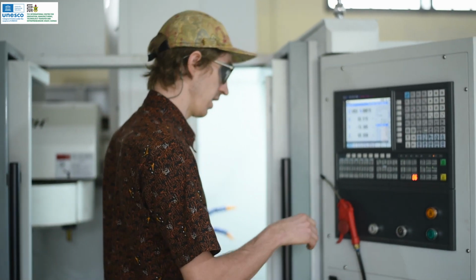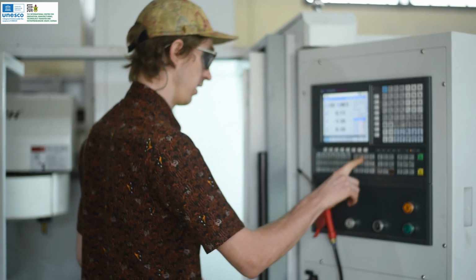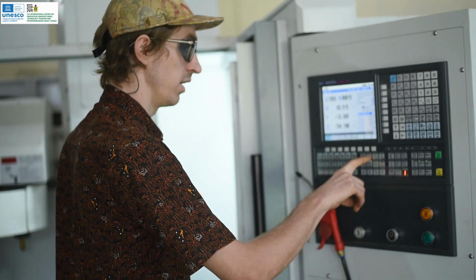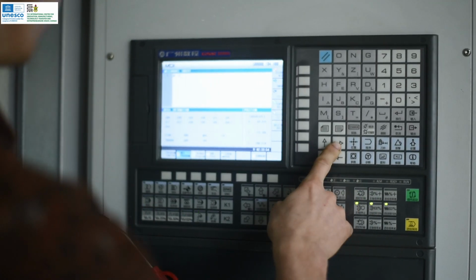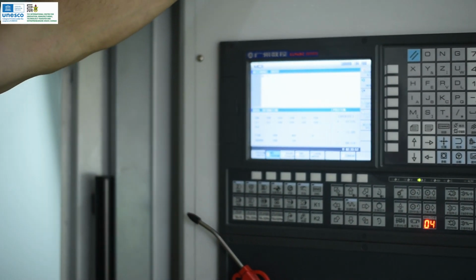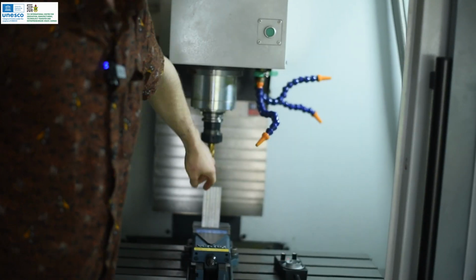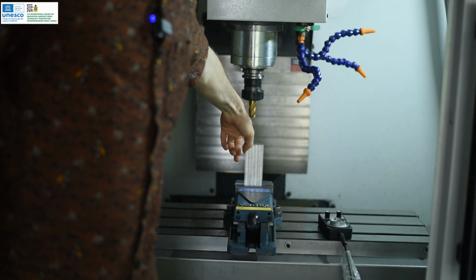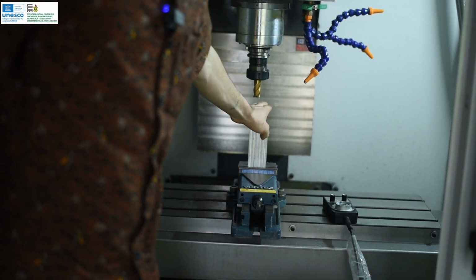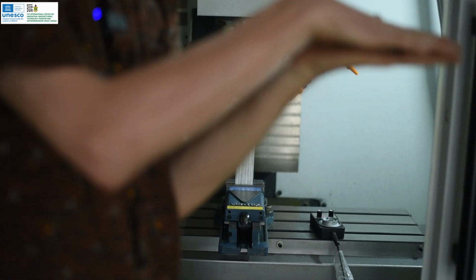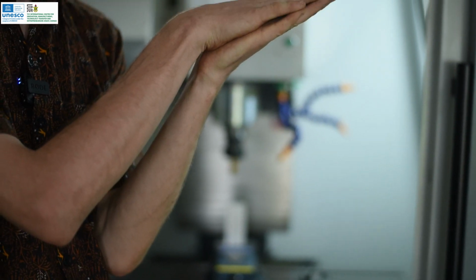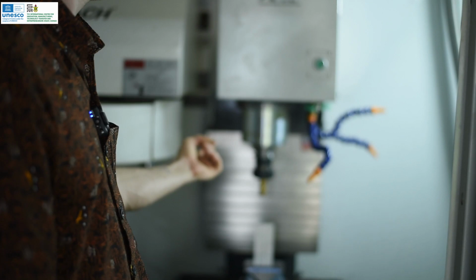First thing we'll do, I'm going to load a tool. Before we load a real tool, we want to use a positive tool length offset strategy. And the way we're going to do that is zeroing the head of our spindle on a known datum. In this case, just the top of this arbitrary piece of squared off aluminum we have. So we'll set that tool length at 0 for the spindle head, and then add tool lengths for each of our set tools to that dimension.